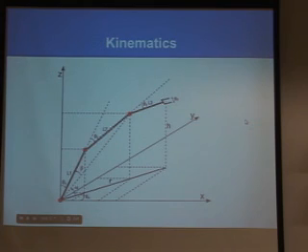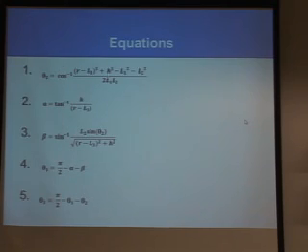So this is our kinematics model. We have 3 links and 3 angles, and we simplified it by setting the last link to be always horizontal. So it's not over actuated, and we have exactly 2 unknowns and 2 equations. These are the equations that we get.